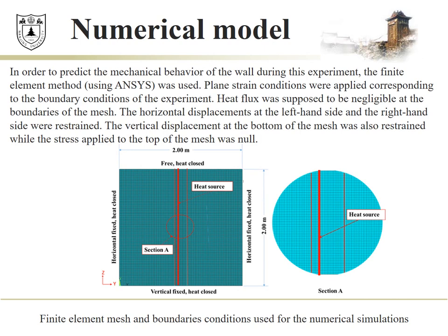The constitutive laws used in this study are summarized as follows. First, only conduction is considered for heat transfer. Second, the mechanical behavior of the wall is linear elastic, while that of the soil is elastoplastic, with the Drucker-Prager yield criterion. Third, the thermal behavior of wall and soil is linear elastic.